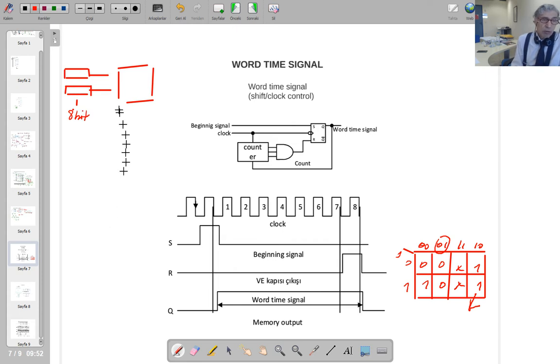When you put in the number to add them up, this number is going to be applied in serial to the input starting from the least significant bit, isn't it? One by one after another, you've got to apply these inputs to your circuit. So it's not easy to do by hand. You're going to do it automatically. How can you make it automatic? Because you know that there is a central clock pulse here, and our circuit runs with that central clock pulse because we are dealing with synchronous circuits,